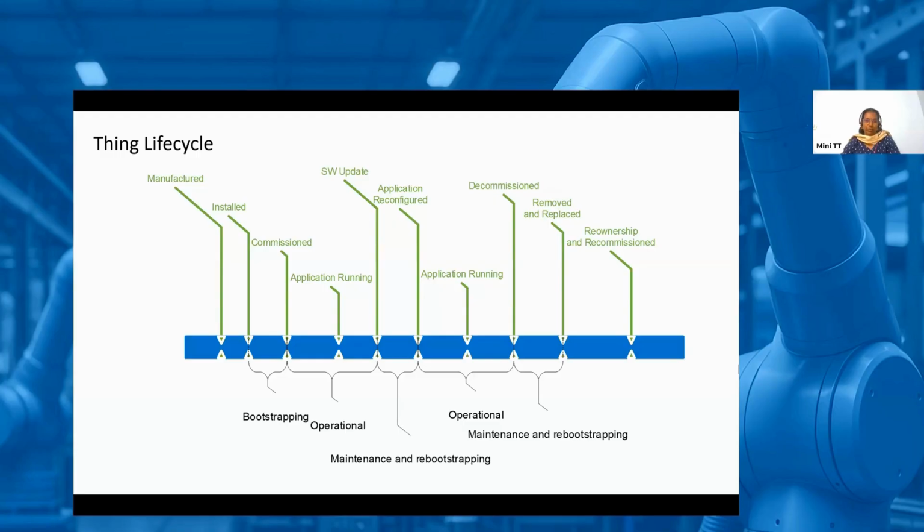All that is what we have to do, both at operational time. Say at operational time, you get a software or firmware update. We have to verify that it is a genuine firmware that we are updating. All that has to happen. That's what we are trying to talk about here. And in this process, how can all this happen with the support from the hardware? Because when we state these kinds of security requirements, it's not possible to achieve all of them only via software or firmware means. We need underlying hardware support also.